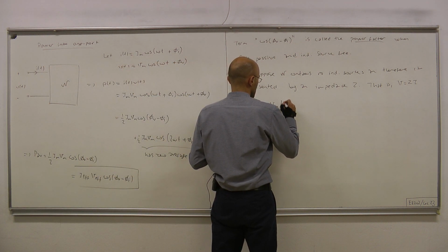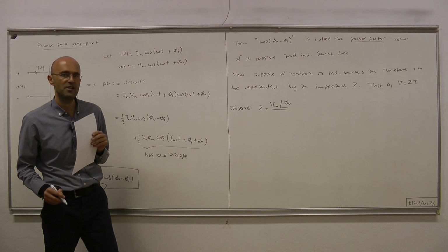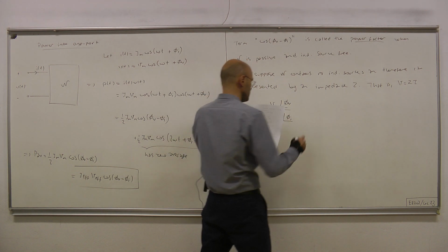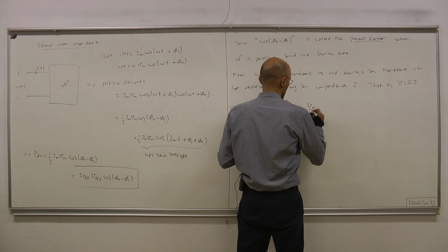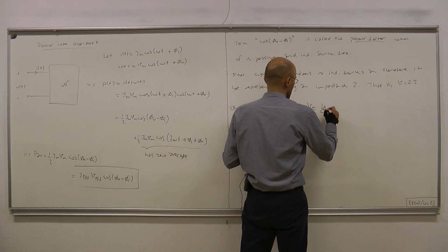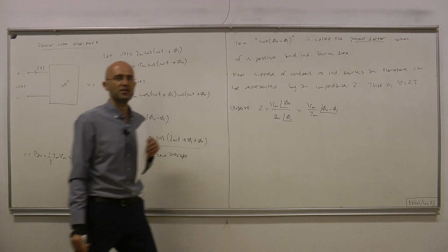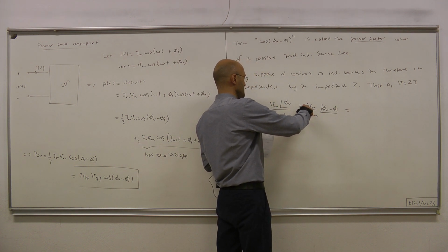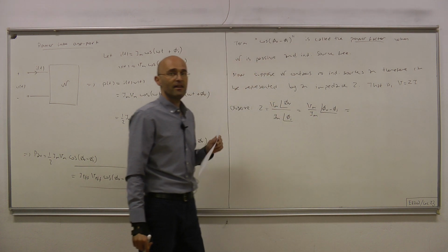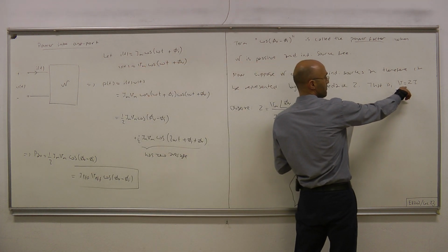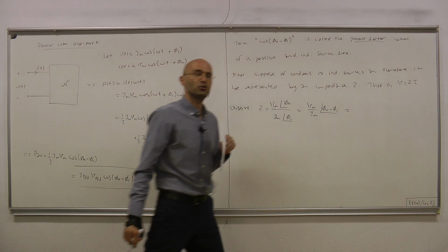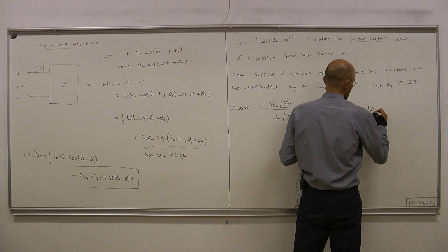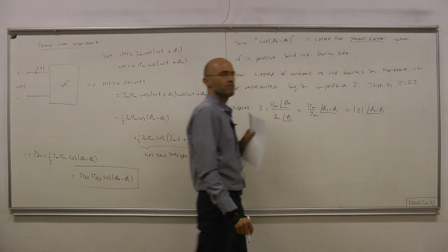The voltage is this, the magnitude Vm with phase phi v, and the current is this, Im with phase phi I. So that reads Vm over Im with phase this difference, phi v minus phi I. This is the magnitude of V and this is the magnitude of I. Therefore, their ratio must be the magnitude of Z, the impedance. This can be written therefore as the magnitude of Z with phase phi v minus phi I.